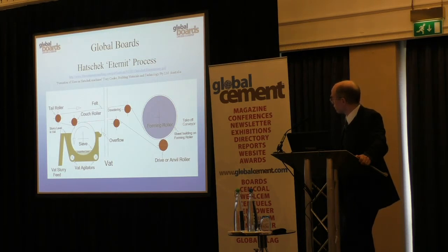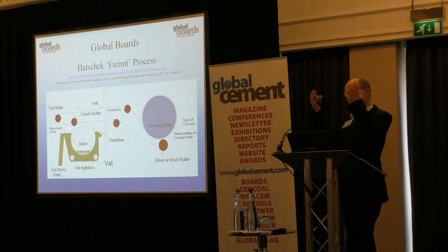The felt belt comes into contact with the top of the sieve, and there's more of an affinity of the thin fibre cement layer with the felt belt than with the sieve. So essentially, the fibre cement layer comes onto the underside of this felt belt, which then comes over the top. There'll be another dewatering process along here, which essentially sucks out the water.